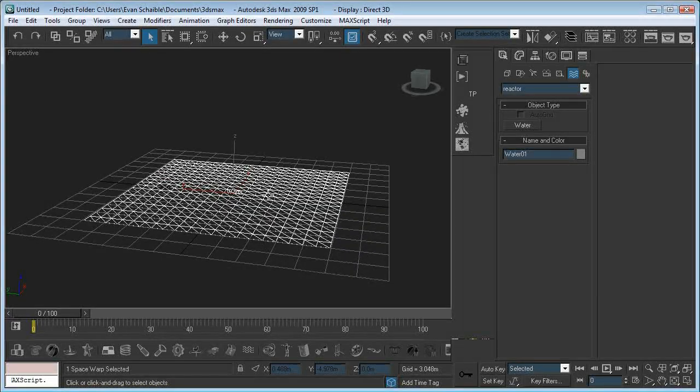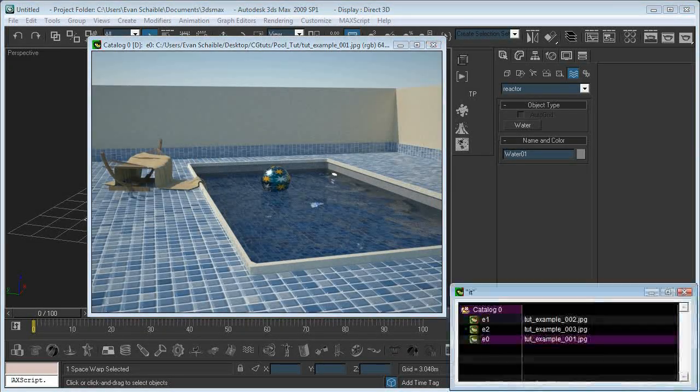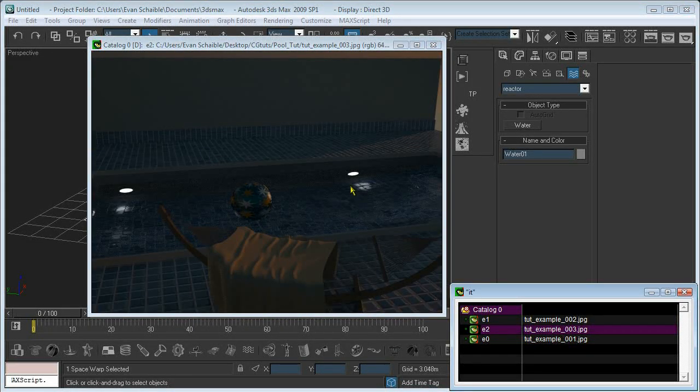Okay, and before we go too far, I want to really emphasize one thing here, because especially in this scene, we're dealing with light sources, and I use Maxwell render as pretty much my main render, but especially for scenes like these. And dealing with Maxwell render, or Indigo, or Lux render, or V-Ray even, or Mental Ray, if they're set right, you're dealing with physically accurate light sources and physically accurate things. And if you're doing architectural visualization especially, you're most likely going to be building most of your things to scale.